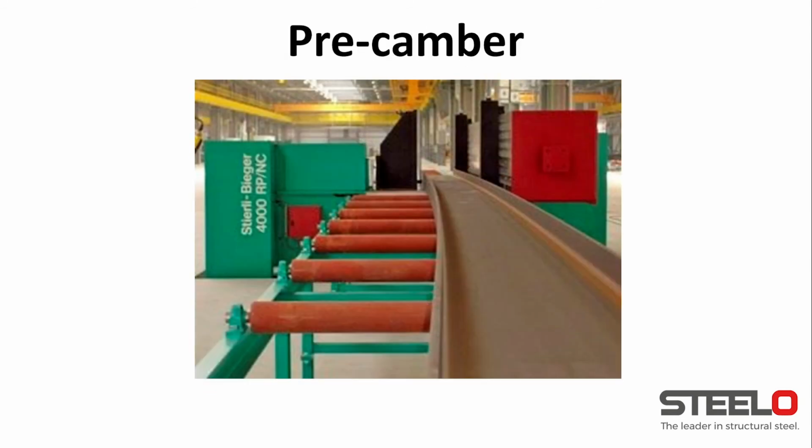A pre-cambered beam is a beam that is cambered. So in other words, it is either rolled very slightly, so it could be that over 5 meters, it only goes out by 20 millimeters or so. The other way, instead of having it rolled all the way, you just might have it bent in the middle. So the machine is different then, because instead of going through rollers, it just goes through a hydraulic machine that basically puts a lot of force into the middle of the beam.